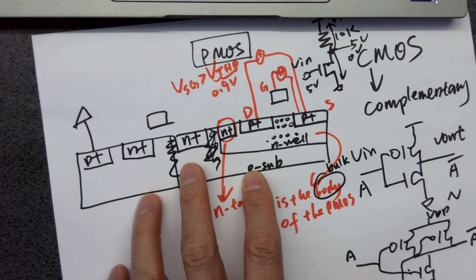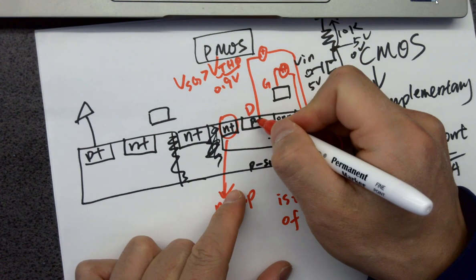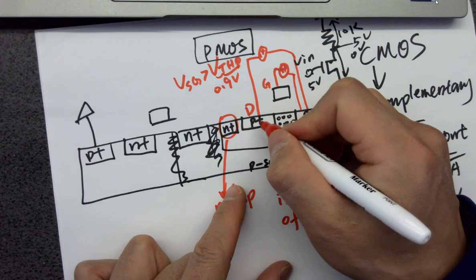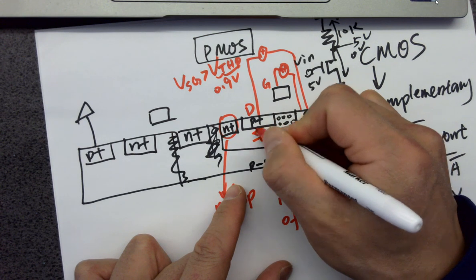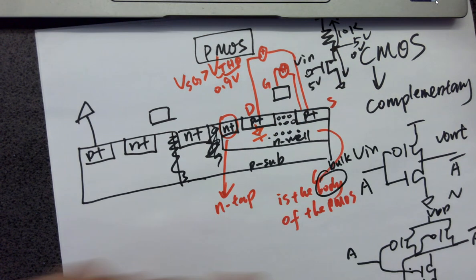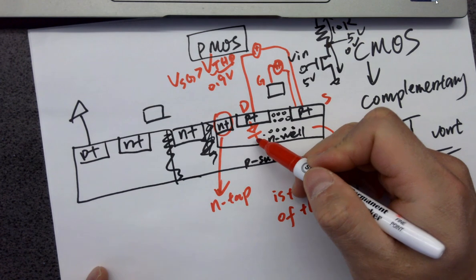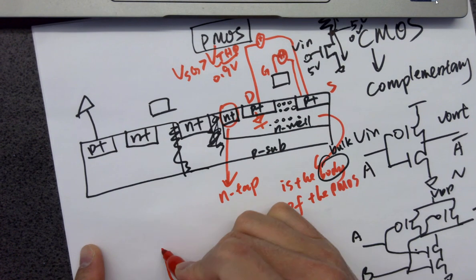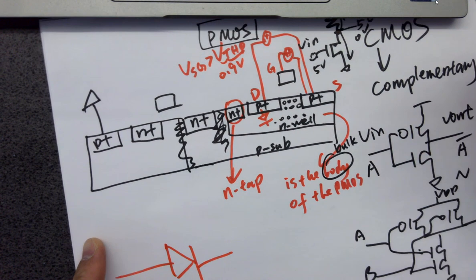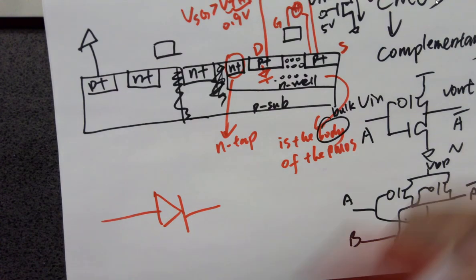Definitely it's forming a diode over here because the P is a P plus and it's an N-well body. So it's forming a PN junction, which is the diode over here. Which means the N-well needs to be shorted to where? Like a diode, I want to always reverse bias it because I don't want to run current through it. It's not a design. I didn't design this diode.